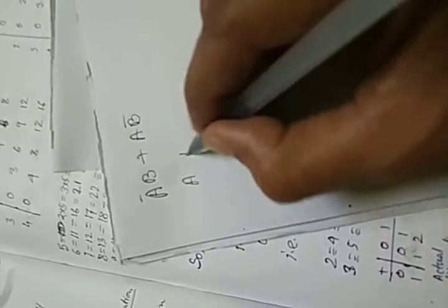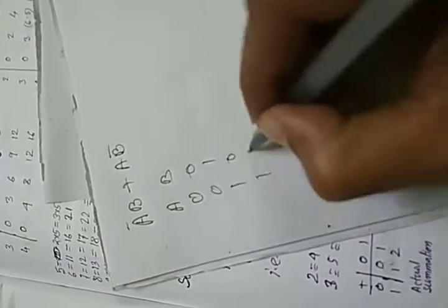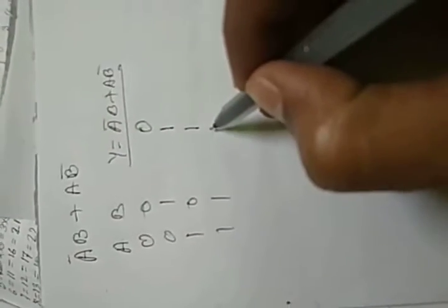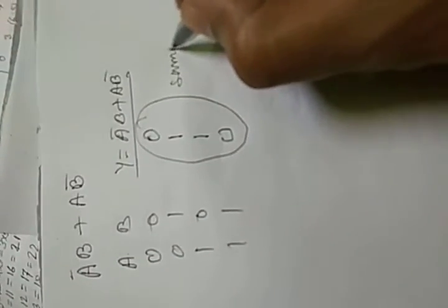So A B, that is 0 0, 0 1, 1 0, 1 1, then output Y is equal to A bar B plus A B bar, that will be written as 0, 1, 1, 0. You know this very well, that is the XOR operation, and this XOR operation output is the same as modulo 2 addition. For this reason, always in case of addition we use the modulo 2 operation, that is modulo 2 addition. Now let us see modulo 2 multiplication.